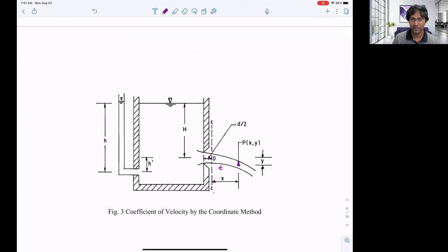What is actually flowing is with actual velocity, not theoretical, right? We'll get the water here at a certain point of time, and we can calculate x. We know x is equal to VA times t, so we can calculate VA as x divided by t.